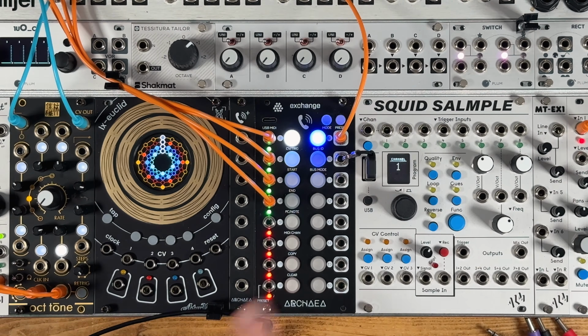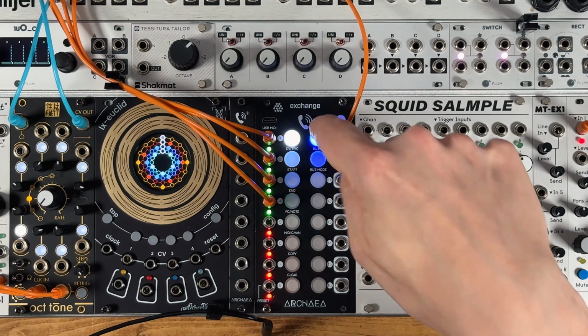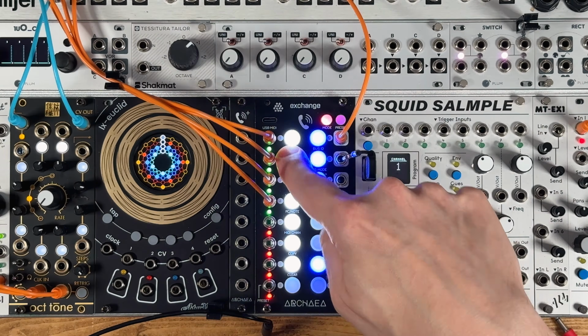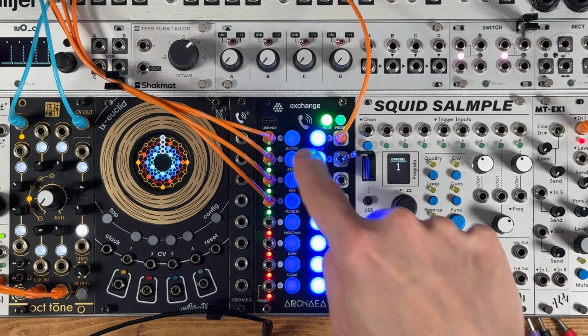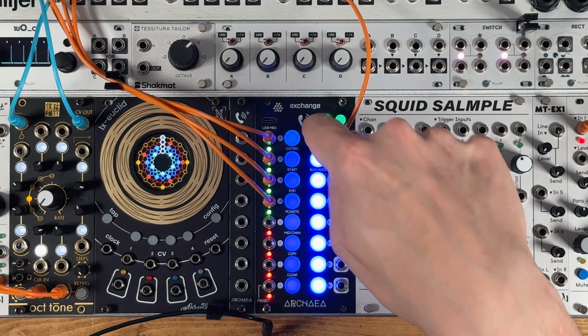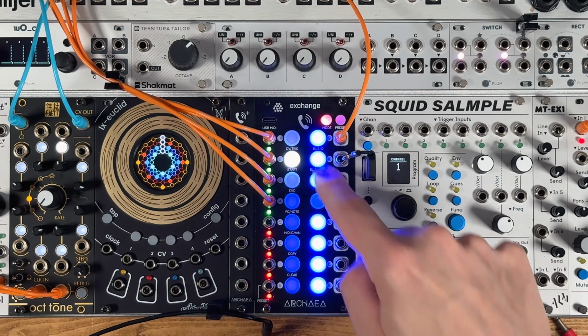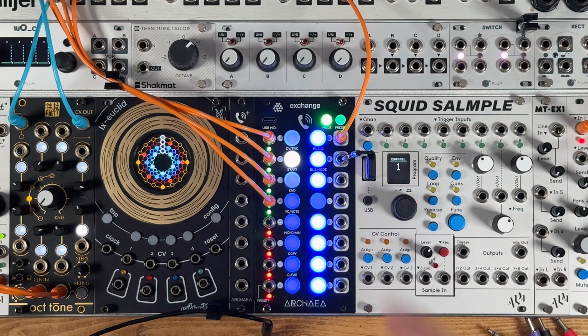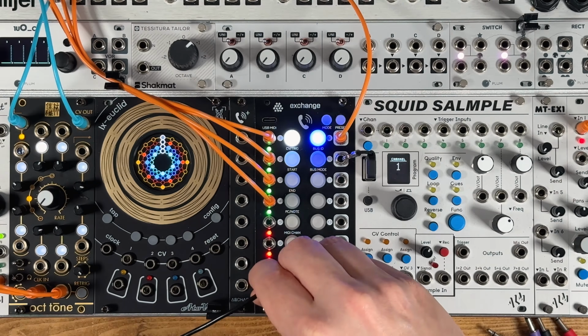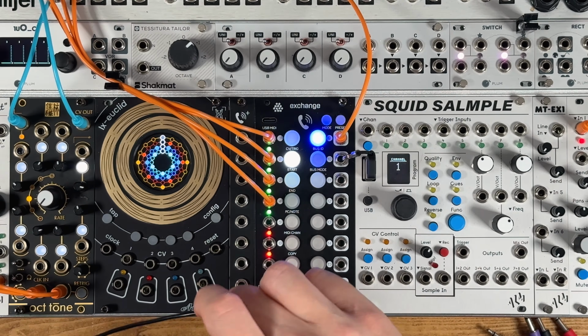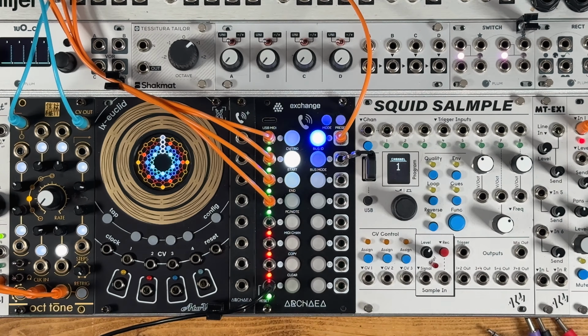And if we want to step through these with an external clock signal, it's just a case of hitting mode, hitting start, and selecting Bank 2 preset 1 to be the start point, hit mode again, then define the end point as being Bank 2 preset 4, hit mode again, and now when I fire a slow clock into input 8 down here, it's going to step through these, so I'll get a couple of repetitions of each one in turn.